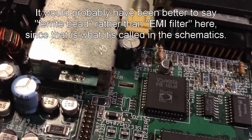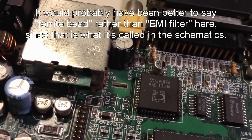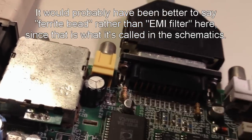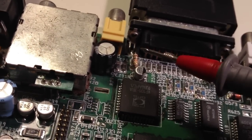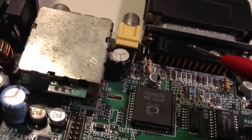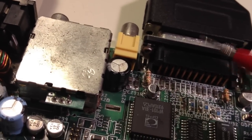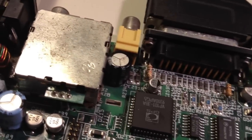Instead, there should be an EMI filter in there, which basically means 0 ohms between VCC and pin 23 here. So that means that if I short this resistor out, then I will restore the 0 ohms between VCC and pin 23, which should bring the picture back. So let's try that.